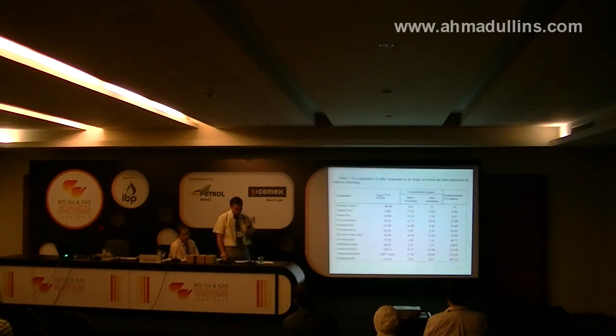Nowadays, processes of oxidative or extractive oil demercaptanization by alkaline solution solve only the problem of deodorization by the extraction and following oxidation of light C1 and C2 mercaptans, in order to satisfy necessary requirements and provide acceptable terms of its transportation in the Russian Federation or abroad. Thus, the sulfur remains in the oil, that is, the sulfur content in the oil is not changed.